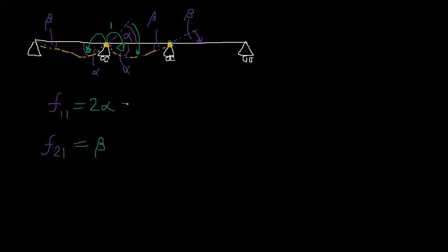So alpha, those are again near to the applied moment. So that is 2 into ML over 3EI. So M is 1, L over 3EI, right? And the beta is the far end, just 1 beta, L over 6EI. Why is our M gone? Because M is equal to 1, right? Okay, so yes, it's done.